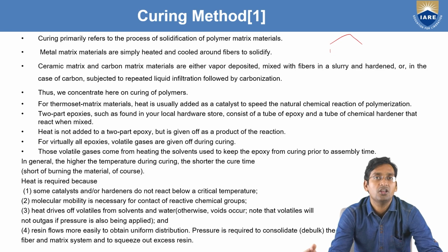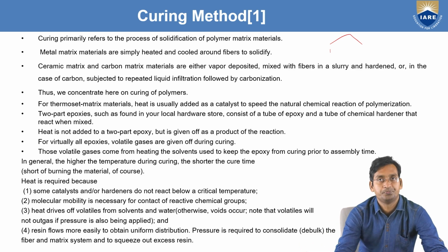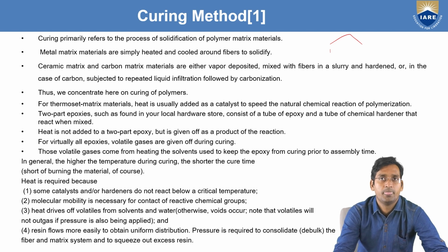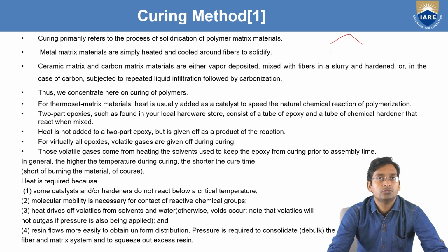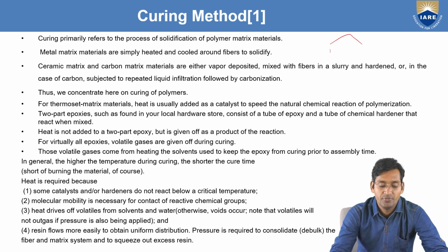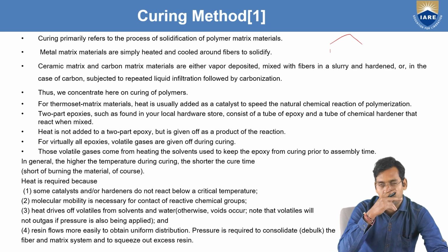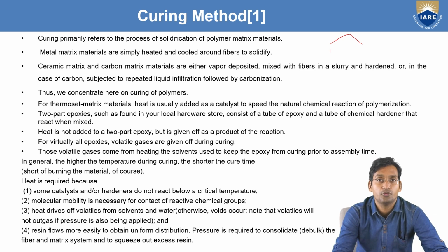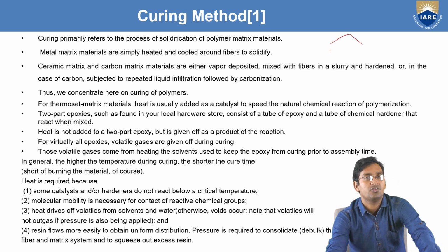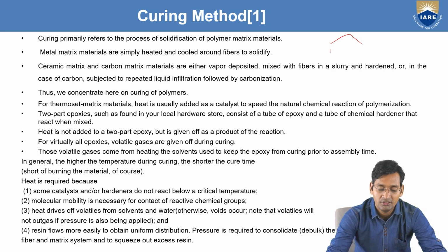If the temperature is higher, the reaction will be fast, so the curing time will be lesser. Why is heat required? Some catalysts and hardeners do not react below a critical temperature. So some are not reacting; once the material reaches the critical temperature, only then will it start reacting. For that we have to supply the heat.